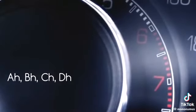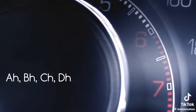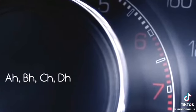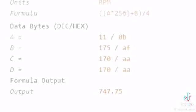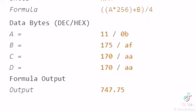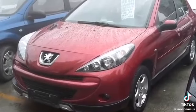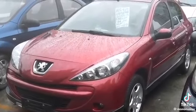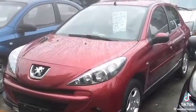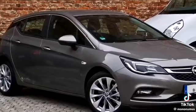A, B, C, D. These are the data bytes in hex, which need to be converted to decimal form before they are used in the PID formula calculations. Note that the last data byte, after D, is not used. Importantly, not all cars support all PIDs, in particular older cars. As such, you may find it far easier to get valid OBD2 data returned in a car from 2015 versus a car from 2007. Yes, we tried.